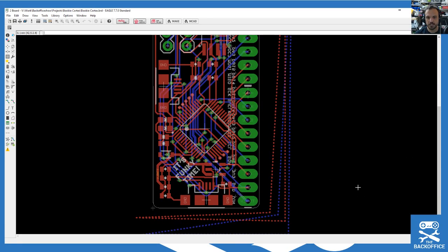So that includes the voltage in. It says VBAT here, but this is whatever voltage is being supplied to it for primary pins. Ground and 3v3. So if you provide a ground and V in here, it'll actually go through the internal regulator and give it the 3v3 supply that the whole board's using.